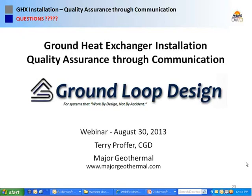The other thing I have a question is, where do you send your grout to be tested? Do you send it to GRTI, or are there other outfits out there that offer that service? Oh, plenty. GeoPro will do it. If you're using their grout, they do the testing for free. If you use someone else's grout, they'll charge, I think, a nominal fee. I don't know what it is, $25 or something. Baroid does the same thing. They test grout. I think there's a bunch of them out there.